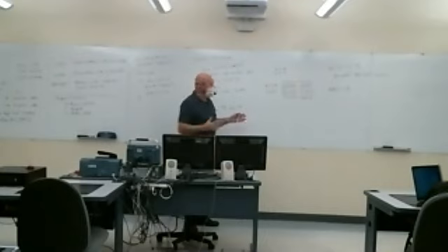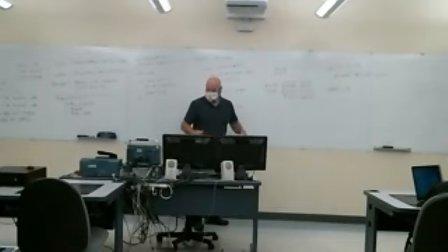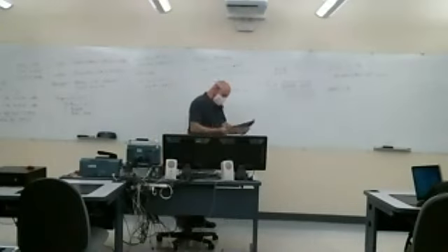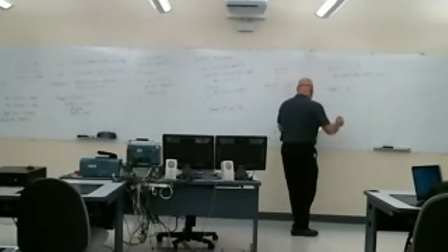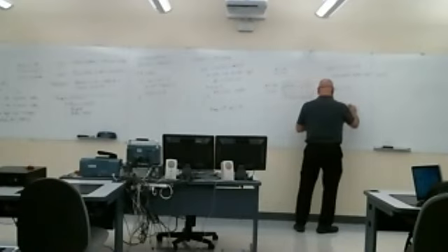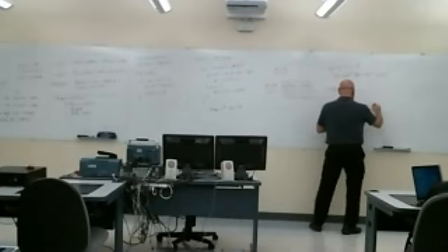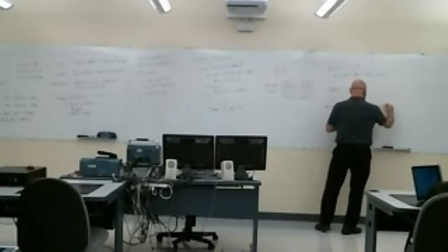He has an example program in here where he toggles a bit every time he goes through a loop. He just wants to flip it back and forth. An easy way to do that is the code he has in this loop, this is program 2.6, but he writes this as P4OUT is equal to P4OUT exclusive OR 0x08.